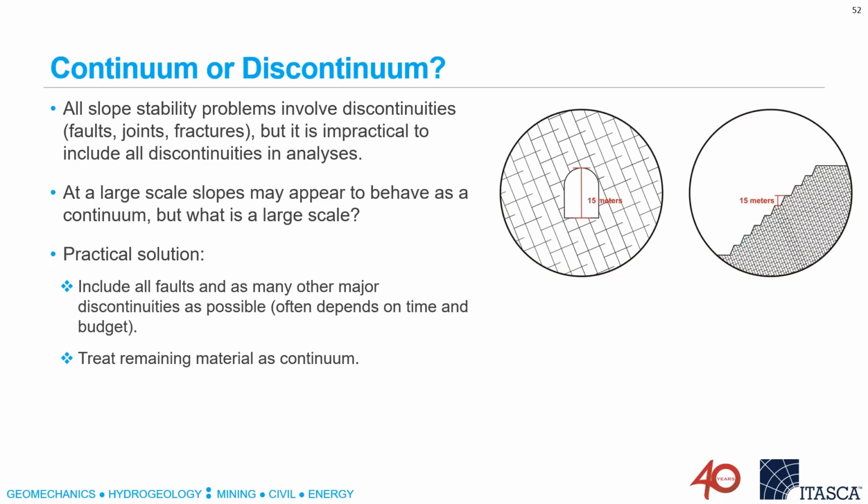So the final thing then is whether we should use a continuum or discontinuum model. And you can see if I take the same structures that I have for this underground excavation and put them into a slope, the picture that you get is much different. This is one with a lot of structures in it. This one doesn't look like it has very many structures. So very often slopes can be analyzed using at least partial continuum representation.